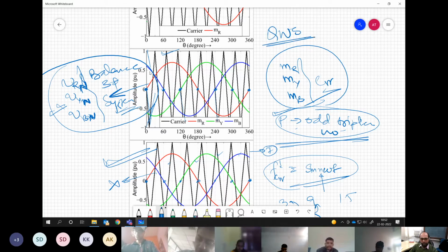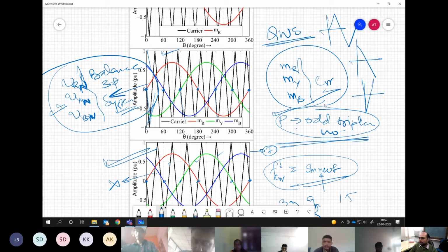If you have any other orientation, the carrier can start from here, it may start like this, it may start something like this. Any of these may still give it, but certainly not this orientation or any other. So the best orientation, what I would suggest to maintain quarter wave symmetry and a little bit better quality, is having this kind of carrier, which is starting going down. Fine.